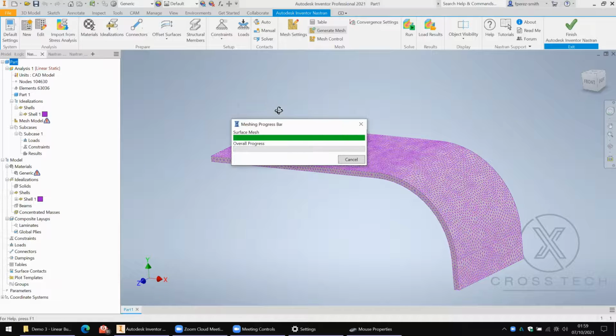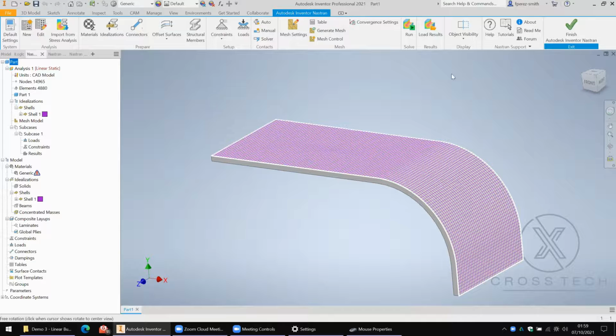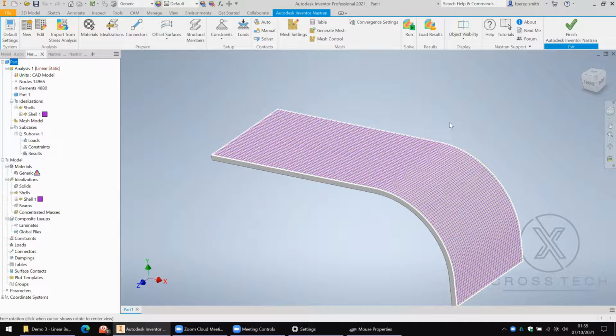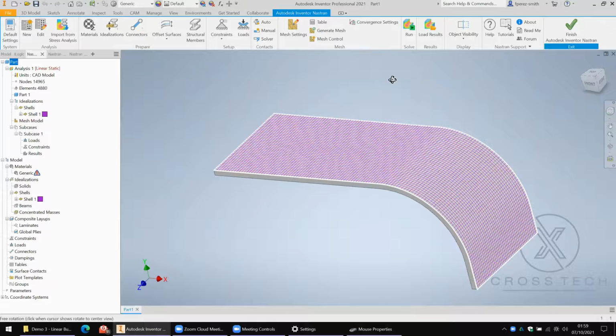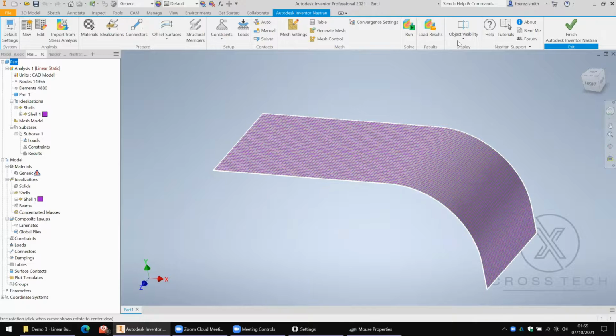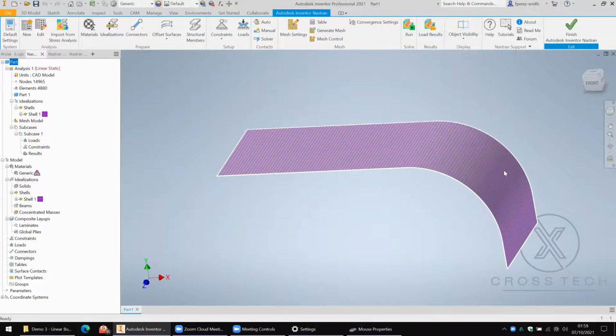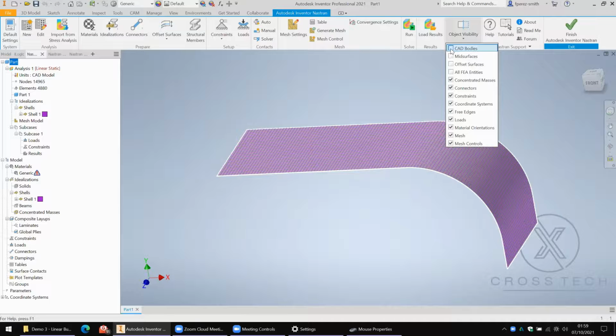Oh, very nice, you'll say. It's a shell, but you look to the other side, and oh, it's gone. I'll disable the visibility of the CAD body, and that's what we're actually dealing with. It's a 2D shell. Now, why might anyone want to do that? Because it's a lot quicker to do a calculation on the shell than using solid elements. These are extremely, extremely useful.